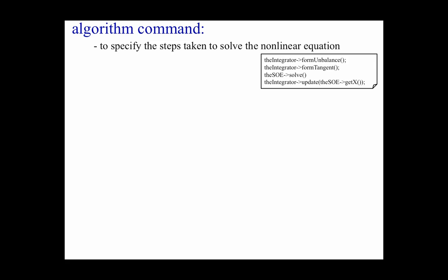Okay, the solution algorithms. If we have a linear elastic problem, or if we're using an explicit time integration scheme, the solution algorithm we want to use is linear. For the linear solution algorithm, I'm showing the code that's implemented on the right. If you actually go look at the code, because of our modular design and how we've set up the system, that's the basic code you'll see in OpenSees. So all we're going to do is form the imbalance.